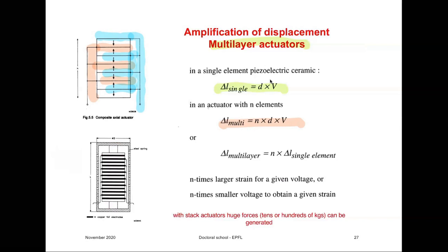Application of the field in one direction is necessary first not to depolarize the material. You can go in a negative direction, against polarization, but not too much. Usually it's about 10% or so against the polarization.